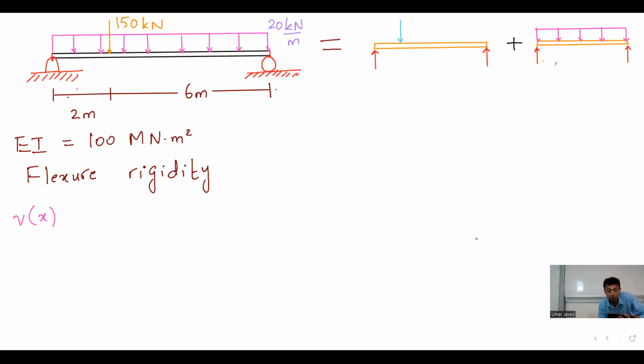So now technically you will have a deflection like this. By the way, deflection will not be maximum here. Ghazal, I think deflection will not be maximum here. I don't think so. You have to find the deflection. That's why I was telling you, don't do it. I think the maximum deflection might be a little to the right of it. So don't automatically think that where the load is, there should be the maximum deflection. That will end up being a mistake. Probably, as I made the diagram, the maximum deflection is a little to the right of it. And then for this problem, yeah, now you are correct. The deflection will be maximum at the center. I actually agree with you now.